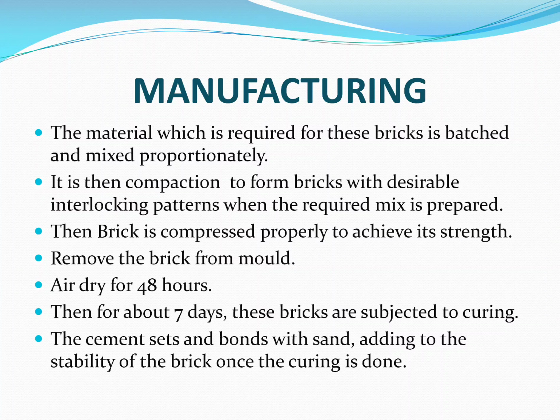Air dry for 48 hours. Then for about 7 days, these bricks are subjected to curing. The cement sets and bonds with the sand, adding to the stability of the brick once the curing is done.